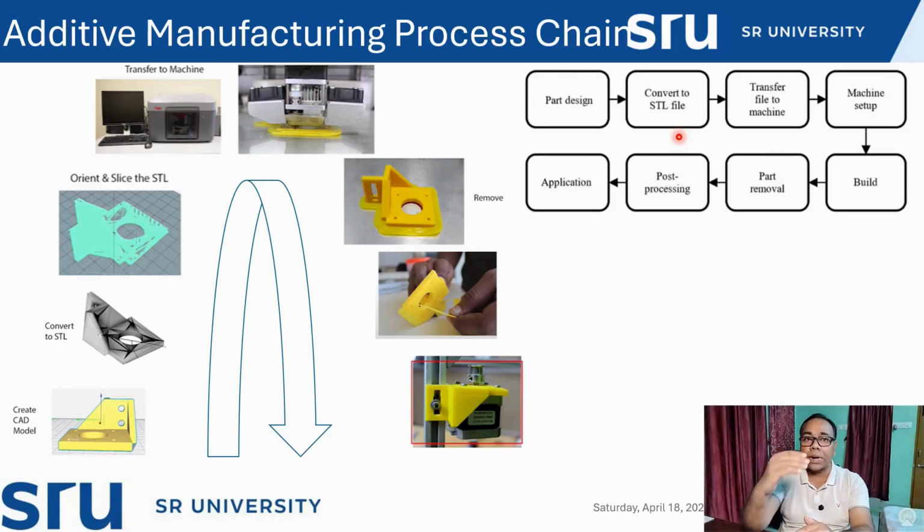Then what could be the height of one layer, so that our build platform can move in the Z direction, up or down? It depends upon how the machine configuration has been done. Based on that, here the slicing will be required. So once slicing is done, from that one can get the entire profile, meaning each layer's contour detail will be received after doing the slicing operation.